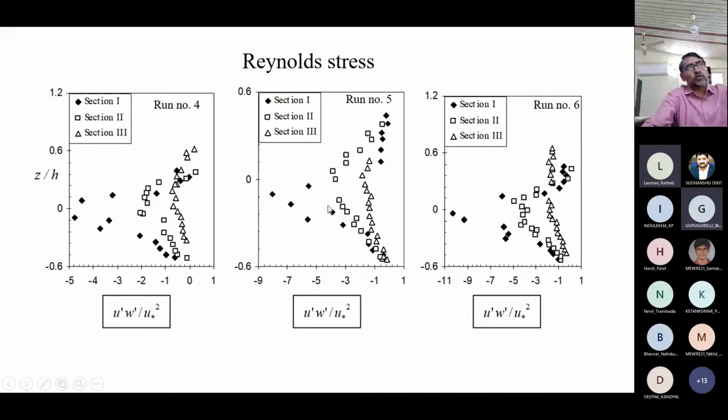As I have shown you, there are a total of 6 runs of data, so whatever calculations have been done, they have been done for all 6 experimental runs. Again in this case, at zy at 0, these stresses and turbulence intensity are maximum. That means at the initial bed level, as sediment is picking up from that bed level, these values are responsible for the sediment picking up, ejection and sweep. That we will also see.